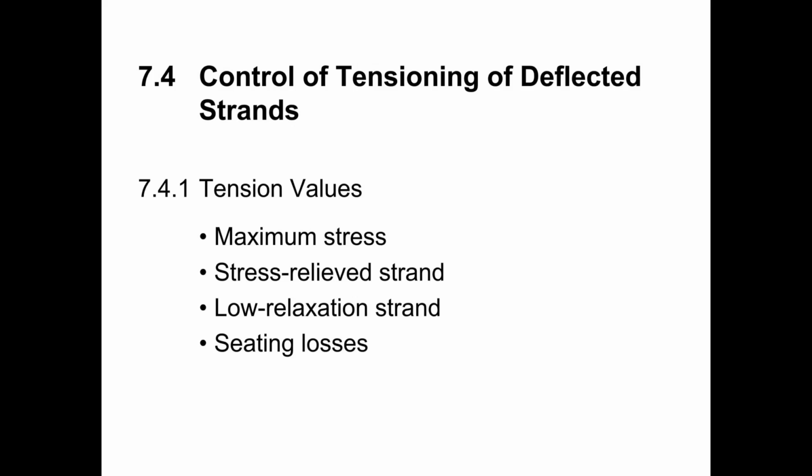All right, in level 2, we talk about losses that occur during the tensioning operation. We have dead end chuck seating losses. We have live end chuck seating losses. If we have a splice chuck in the setup, we have a loss associated with that splice chuck. You may have losses associated with bed shortening if it's a self-stressing bed. If it's an abutment type bed, you may have losses associated with abutment rotation. There are potential losses associated with changes in temperature. Again, if it is an abutment type bed, you may have temperature corrections.